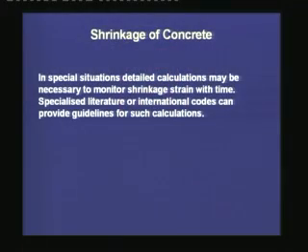In special situations, detailed calculations may be necessary to monitor shrinkage strain with time. Specialized literature or international codes can provide guidelines for such calculations. The shrinkage is of a concern for liquid retaining structures, where shrinkage cracking can be a problem because the liquid can come out or can percolate out through those cracks, and that will lead to a problem of durability of the liquid retaining structure.